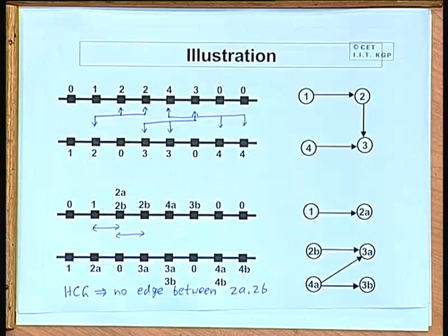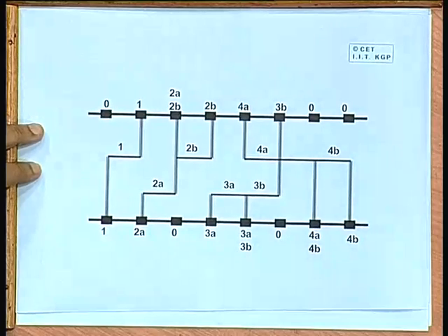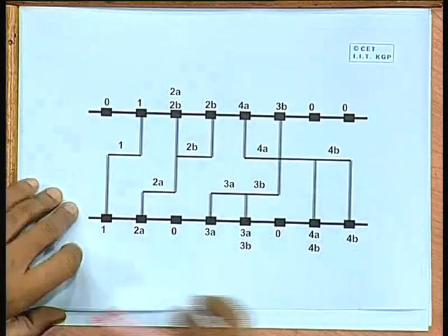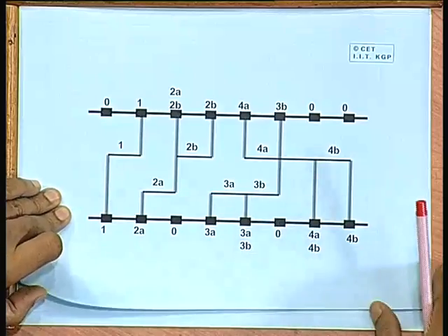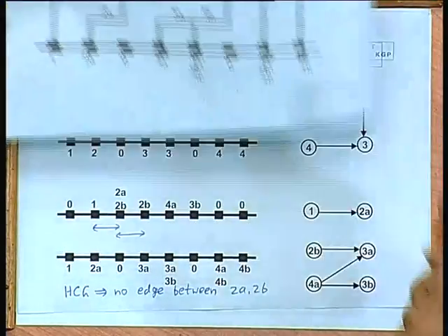Fine. So, once you do this, for this problem, if you apply the extended left edge algorithm, the solution comes like this. Start from left to right, you just again look back at the constraint graph just to see in which order you have to consider.